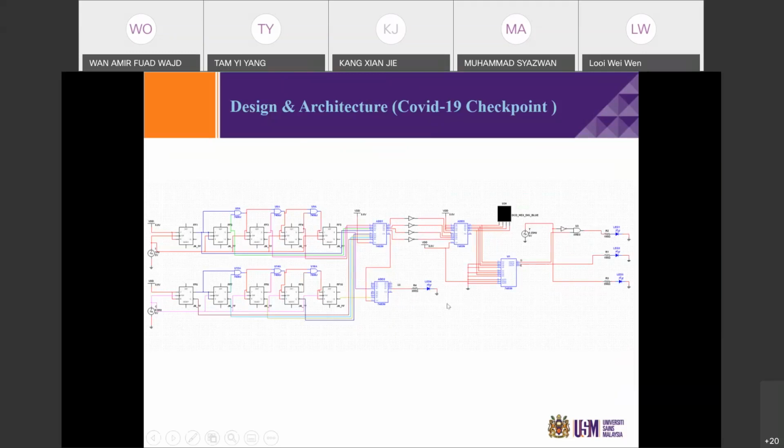Then we'll show how many seats are still available in the vehicle by deducting the total people on board from the maximum limit capacity. In this case, the limit of the vehicle is set as 15. Therefore, the output of the third adder, which is the total seats still available, will connect to a 7-segment display so that the passenger can know whether there are still available places.